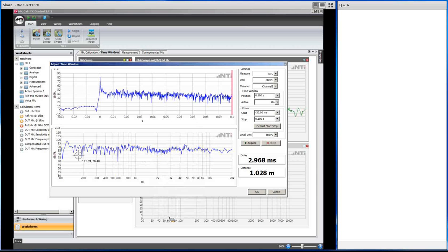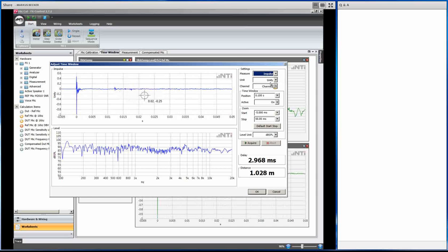You see a lot of ripple in this frequency response, and this ripple is of course not coming from the microphone. This is the impact of these room reflections. The overlay of these room reflections to the direct sound causes this ripple. And we see that also here in the energy time curve. Alternatively, I could also show you the impulse response. This is just a different way of displaying this incoming signal. And here we see also these reflections. This is the direct sound from the speaker to the microphone, and these are the room reflections.